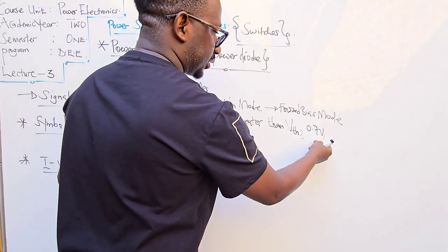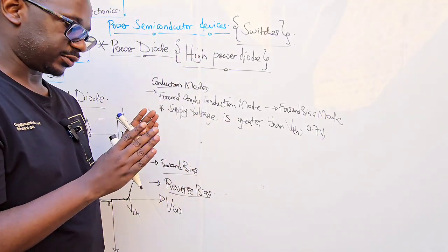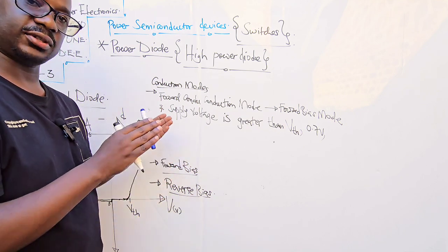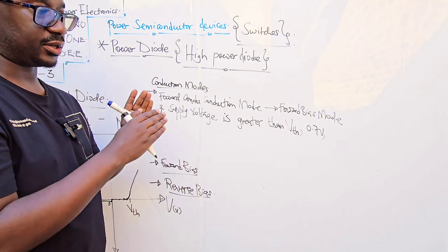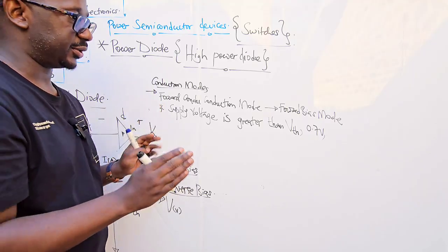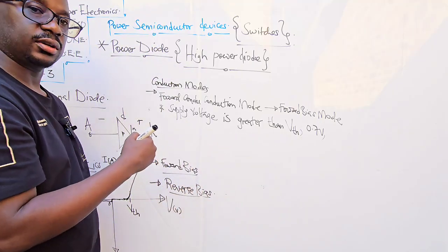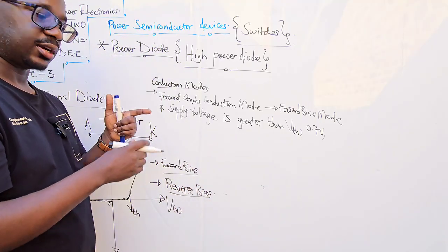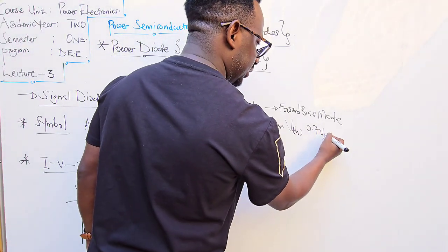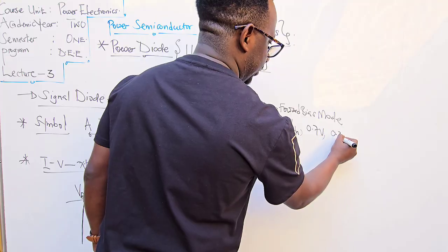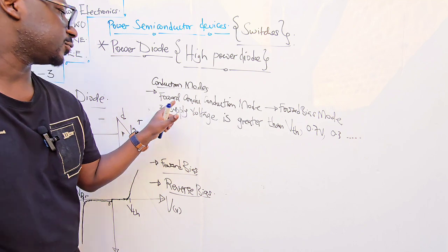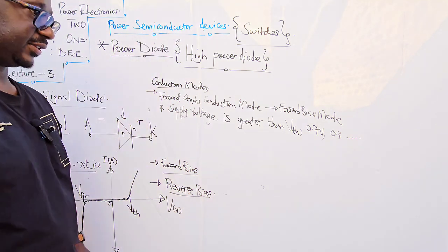Since it has electrons or charge carriers, because there are holes and electrons, positive charge carriers and negative charge carriers, they create a voltage, or a potential difference, across that region, and it is in opposite orientation to the supply voltage being applied to the diode that is in forward bias. And that voltage happens to be around 0.7 and 0.3 and smaller voltages depending on the material that's used to make the semiconductor device.